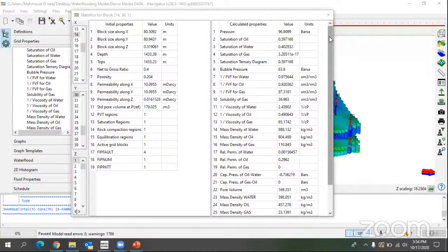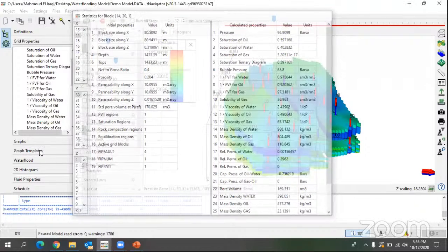So actually we have to divide the reservoir into a reasonable size, because dividing it into very small grid sizes will make it computationally very hard to calculate the reservoir production data that we want to predict. And you don't do it one time, you do it a lot of times. As I said before, it's an iterative process. You can do it like 50 times before you get a good match. So it can't be tiny grids, so you can make it more reliable to do your calculations and do the future prediction.